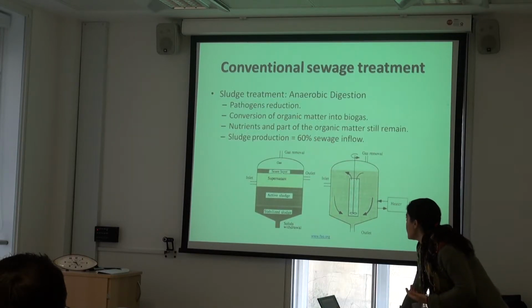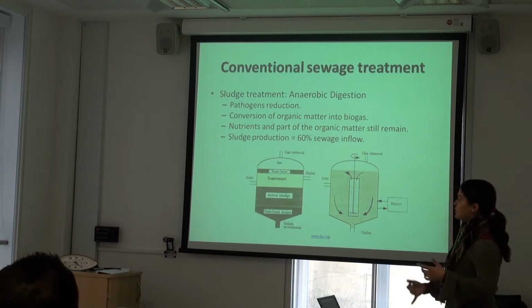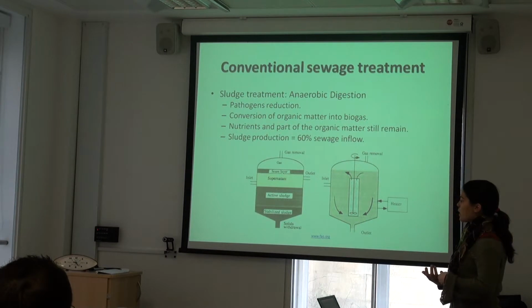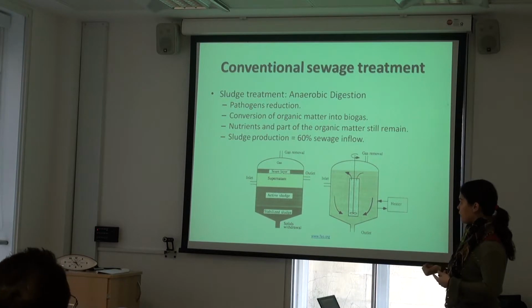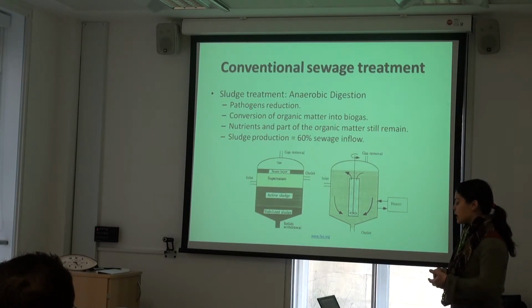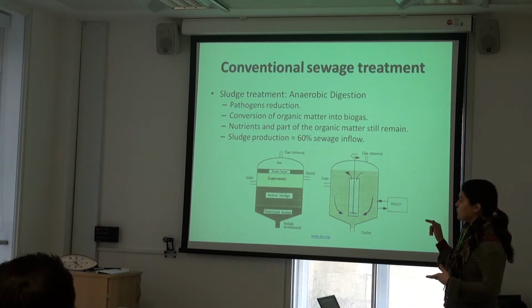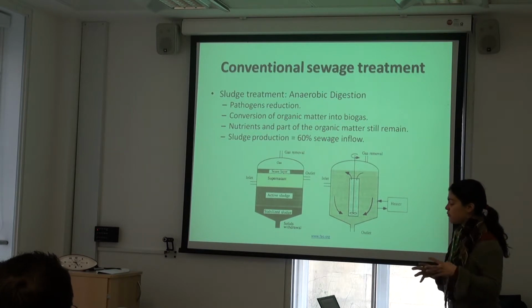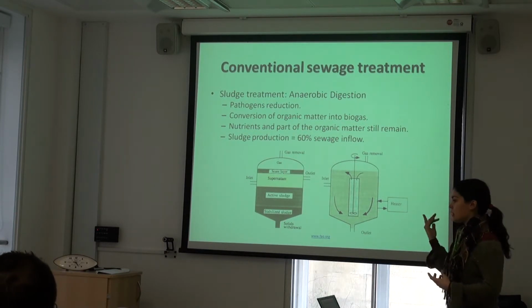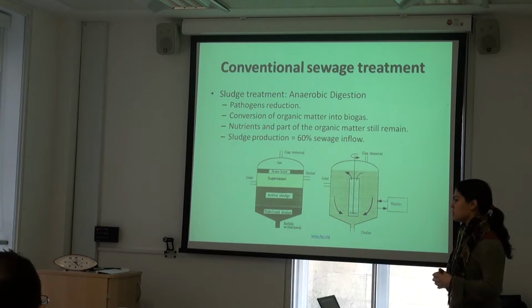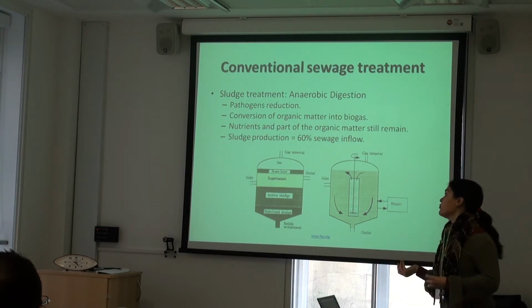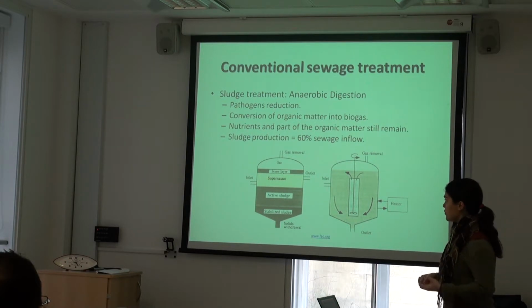This is generally done through anaerobic digestion, which has first the aim of reducing pathogens, because very high temperatures are generated, the pH also changes, and acids are generated and so forth. And you can also get methane out from here, which normally is used on site to heat these and also in the plant. For instance, the most expensive part of wastewater treatment is to aerate. So right now this doesn't make up for all the energy costs, maybe 40% of it, which is not bad. But this could be improved, and then everything would be much more cost effective.